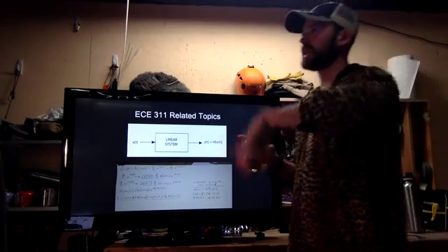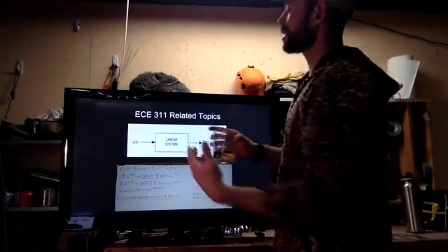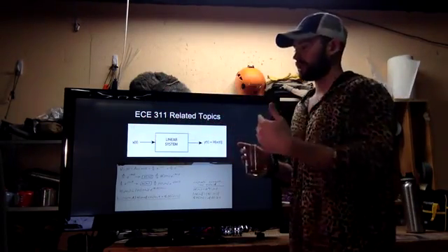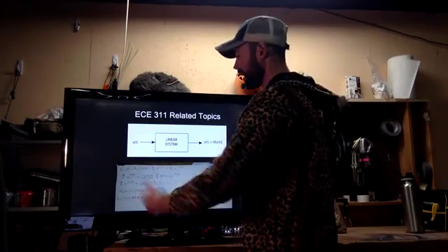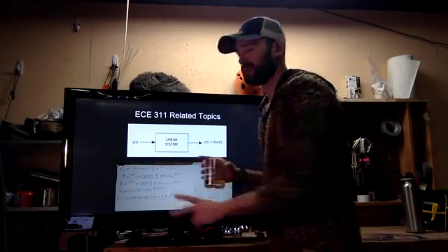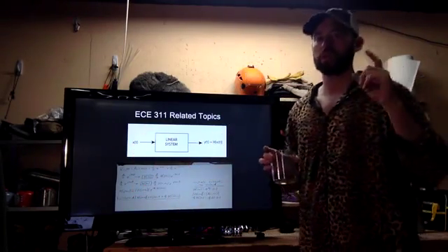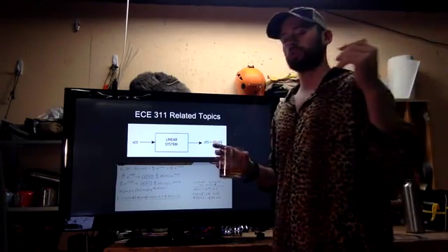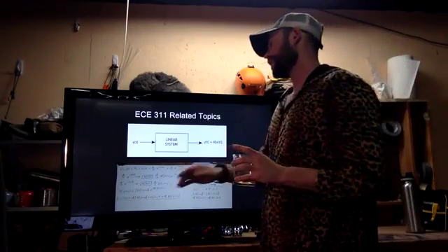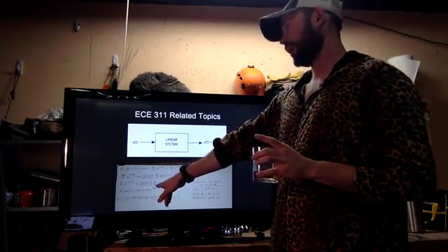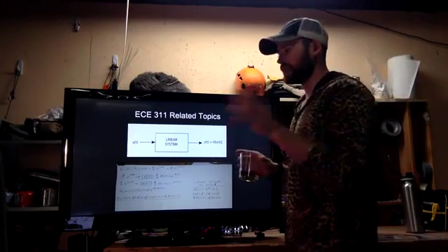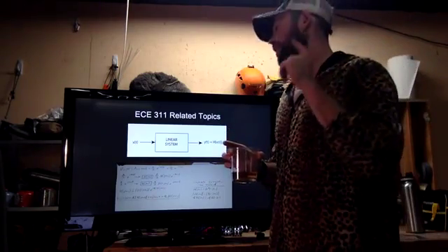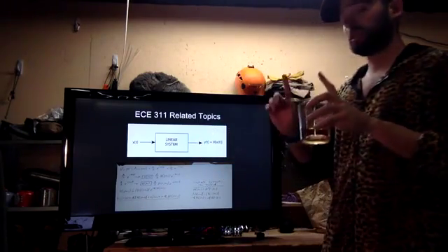And so since we're sending in a periodic function and we're approximating a linear system, we expect to see a periodic signal coming out. When you put in a cosine, you actually split it up into its two components of e to the j omega naught t and e to the negative j omega naught t. When you put those through the impulse response, you get out a certain output. The definition of h of j omega naught is the magnitude of h of j omega naught times e to the j phase of h of j omega naught. That's the two components of it.